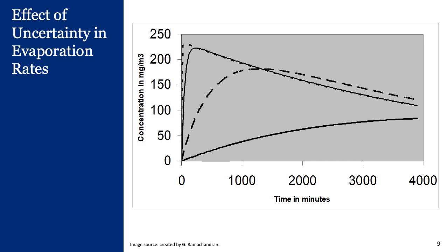Likewise, when we have an alpha of 0.0002 per minute, the concentration is now increasing, and it hasn't even reached its maximum as predicted by the well-mixed room model when the weekend is over and the employee opens the door. And so now the concentration has just reached about 84 milligrams per cubic meter.